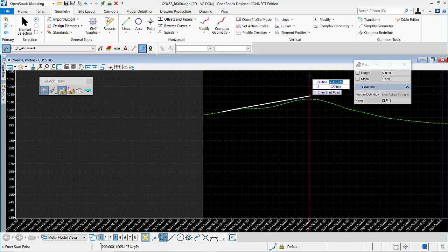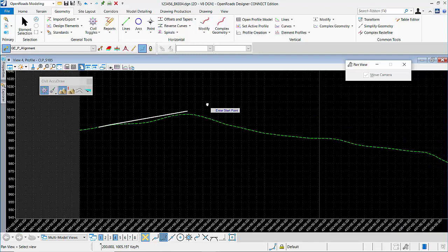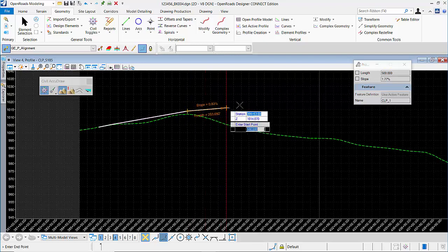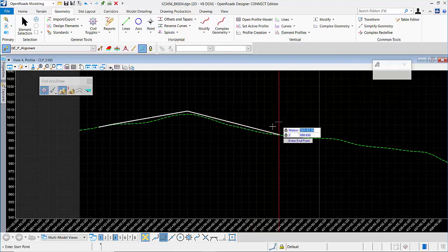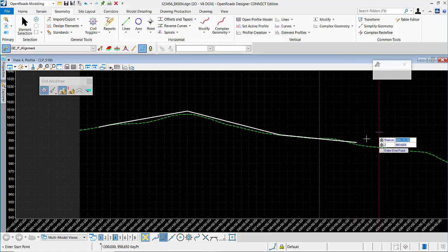So I'm going to continue entering stations and elevations using ODOT's training material with the values that are given there on page 401-2. So I'm going to start from the end of this one. And the next one is at station 398. An elevation of 998.65. Accept that. Starting from the end of that one, we're going to station 403. An elevation of 993.65. Accept that.